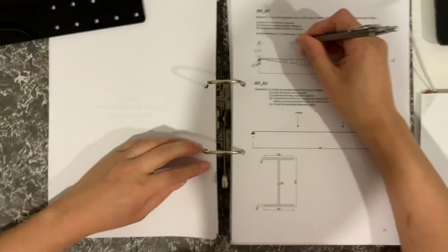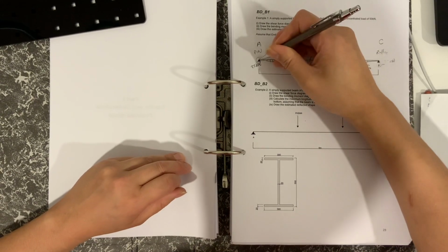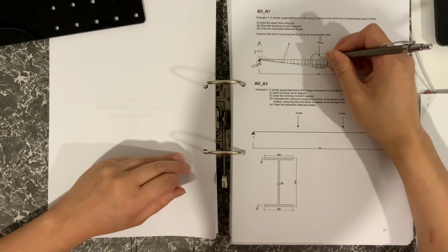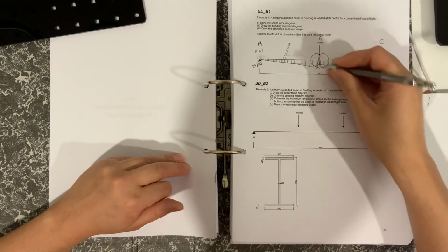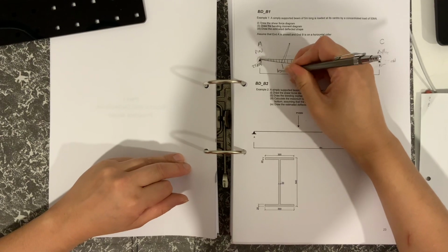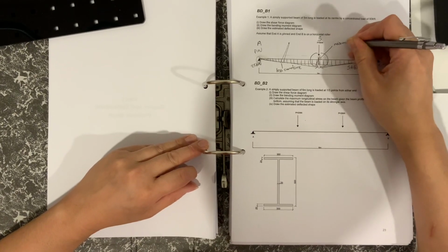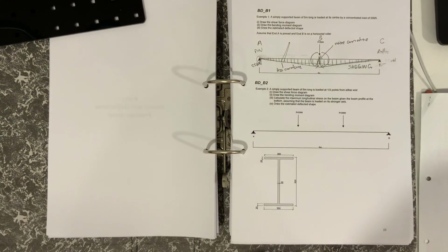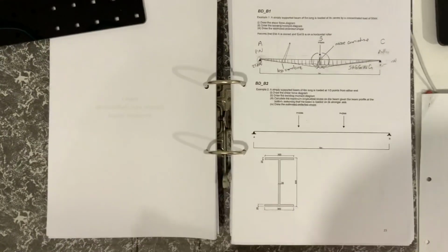And right here, maybe I'll try and illustrate the radius of curvature. If that had been the deformed shape going round like there, then when you get down here, the radius of curvature is much smaller. So there would be less curvature here, there would be less curvature there, and there would be more curvature there. Okay. So next question is a simply supported beam loaded at midpoints.